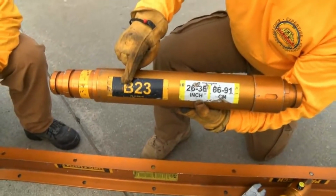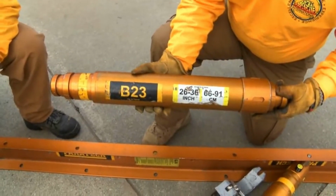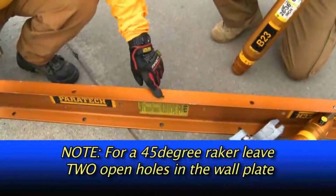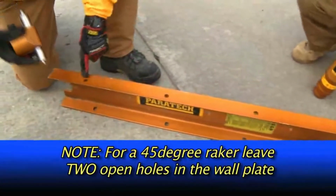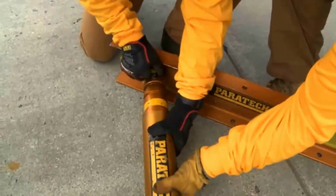Now assemble the bracing. Use a B23. The B indicates it is a brace. For a 60-degree raker, leave 3 open holes on the wall plate. Attach the raker latch base to the 4th hole. Remember, yellow tape goes to the wall. Take the brace with the yellow tape and attach to the wall plate.